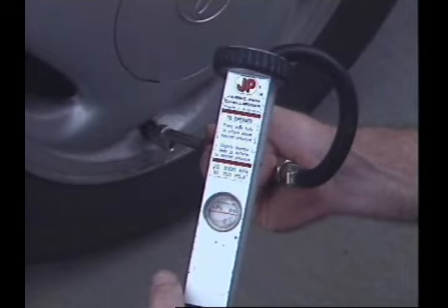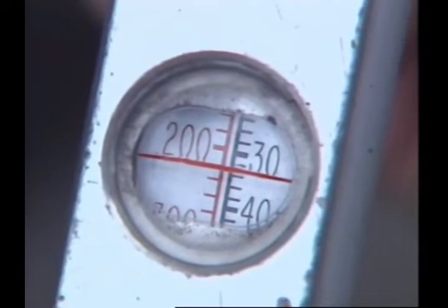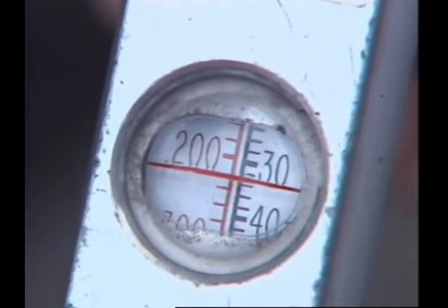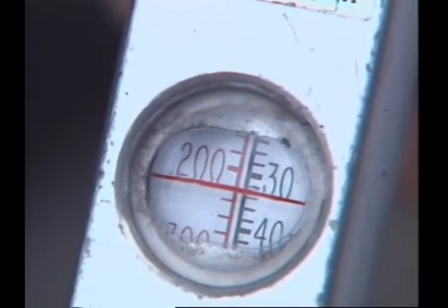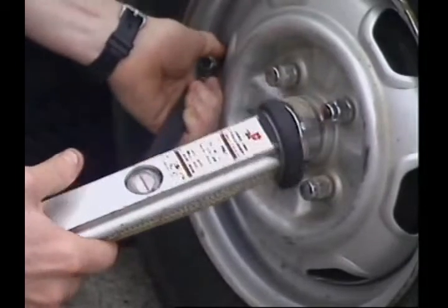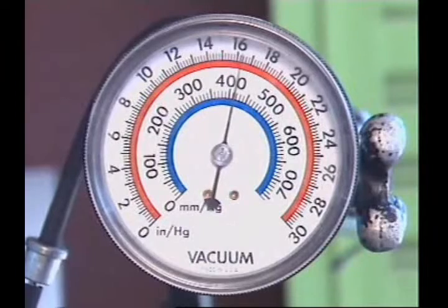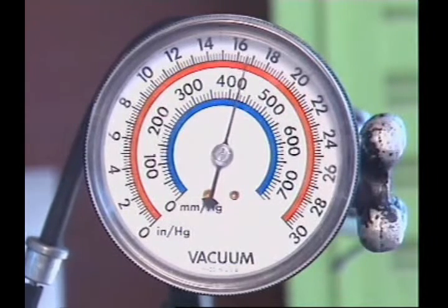It is normal practice, however, for the gauge reading alone to be taken as the accepted value. If pressure being measured is below atmospheric, a pressure gauge with its 0 reading is of no value. This is why, for pressures below atmospheric, as in a manifold vacuum or depression, a vacuum gauge is normally used.